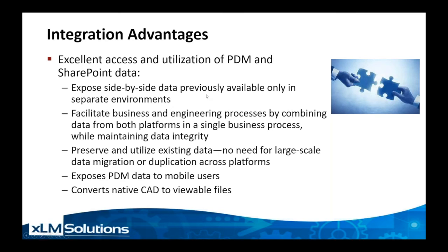And to pause and just get a little commentary here, when we're obviously talking about a SolidWorks PDM to SharePoint integration, there's different ways to skin the cat. Maybe the answer is don't use SharePoint at all, and use SolidWorks PDM as your core repository and have all users go into SolidWorks PDM to access all the data in one place.